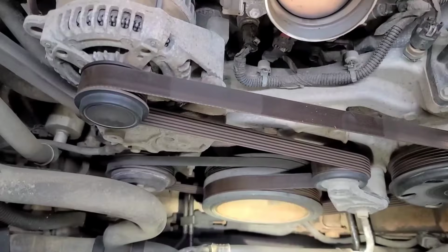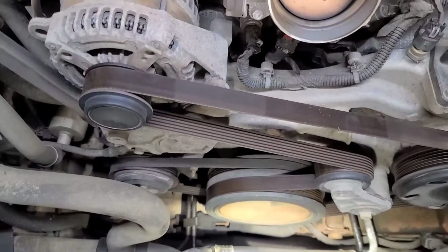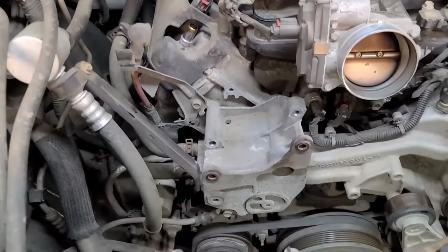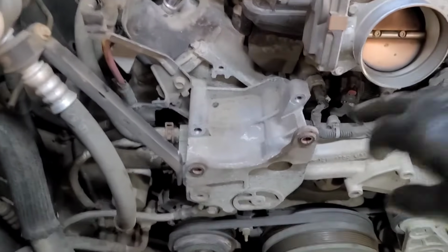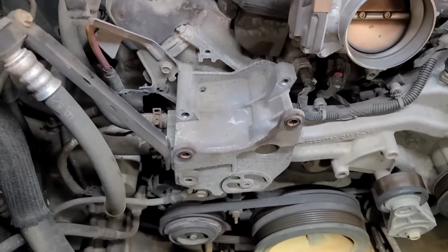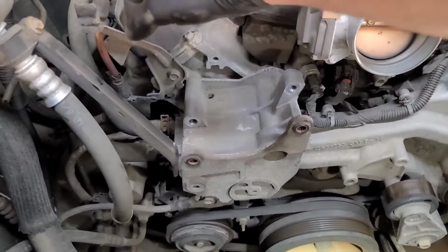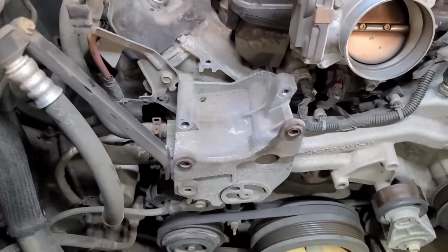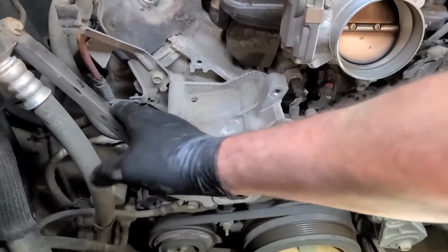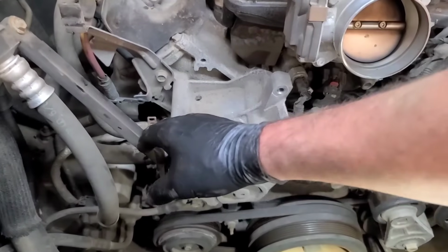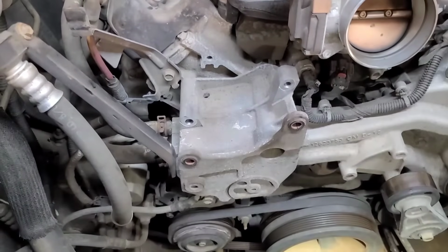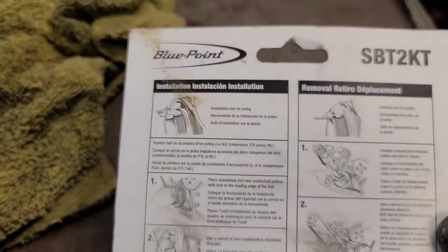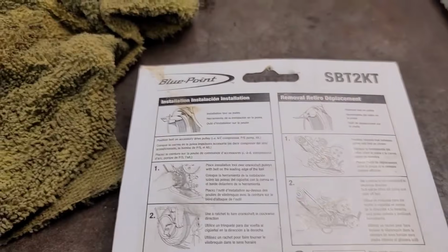So we're going to disconnect the battery because it's just a wise thing to do with all these intrusive repairs. So the next step is to remove the alternator. Two bolts, different lengths by the way, pretty obvious. The cable and the electrical plug, put the alternator aside. And we're going to remove this brace and leave it attached to the AC line, and drain the cooling system now.